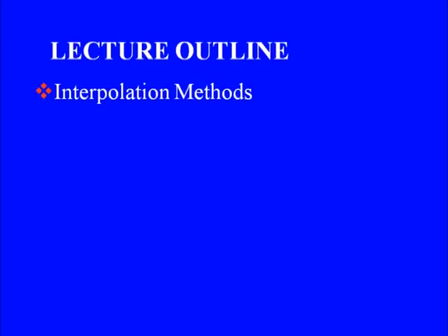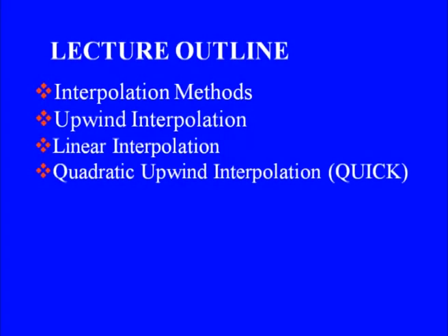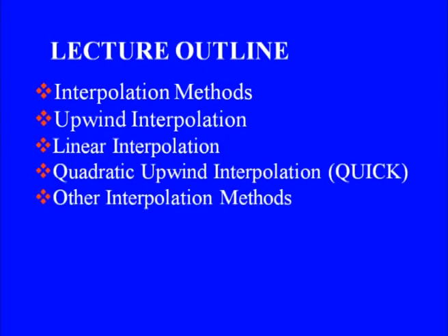So, a brief outline of the lecture. We will have a look at why we need interpolation schemes in the finite volume method, and then a few of the most commonly used interpolation schemes, namely upwind interpolation, linear interpolation and quadratic upwind interpolation. We will also have a very brief look at other recently developed interpolation methods.